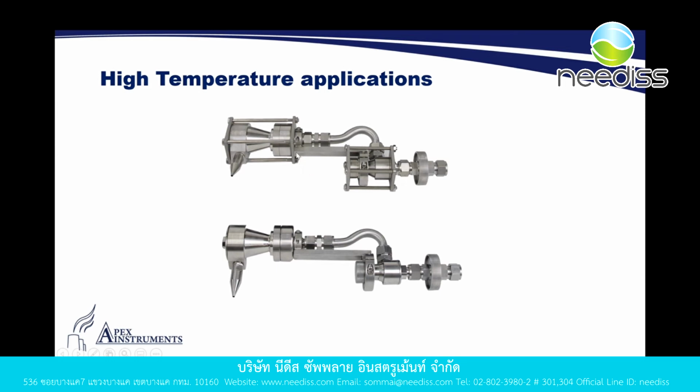Now, the advantage of this is that if the stack is very hot, you may get these bolts here to gall, and you may not be able to remove these bolts, but you will be able to cut these particular bolts right here to get to your sample. It is much less expensive to replace these 4 bolts than it is to replace this entire cyclone.